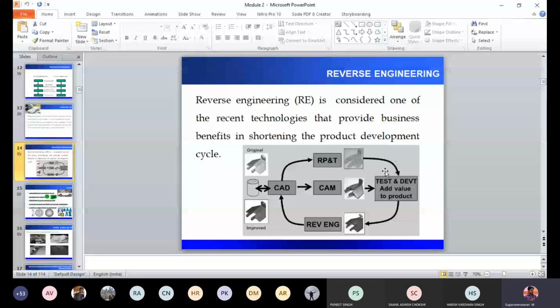The forward engineering is you have a dimension. Based on the dimension, you create a CAD model. Then using a CAD model, you have two options. You can transfer the CAD model to additive manufacturing to get a component. The CAD model can also be transferred to traditional manufacturing. Computer assisted traditional manufacturing is CAM, computer assisted machining like CNC, VMC, vertical milling center, lathe with computer assistance. The computer will read the data from CAD and automatically generate a program for the machining activity, right? So that is a CAM process. So reverse engineering plays an important role in CAD, CAM as well as additive manufacturing processes.